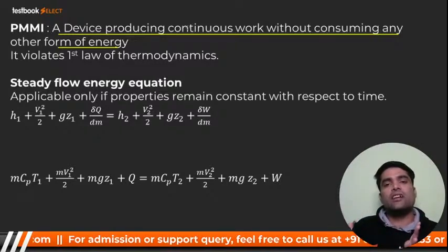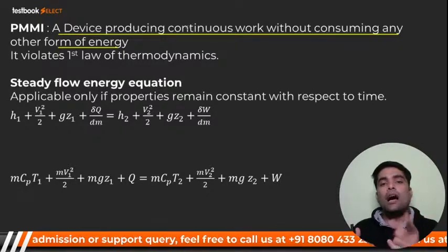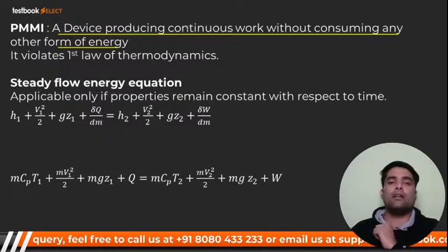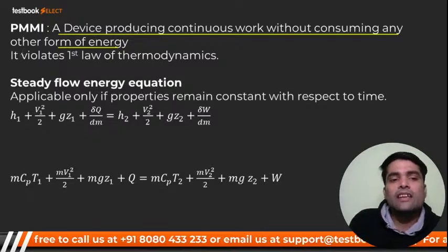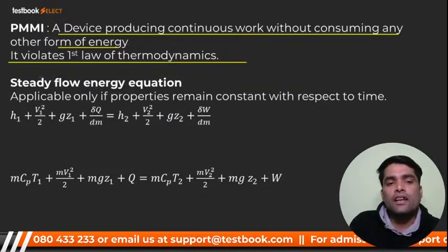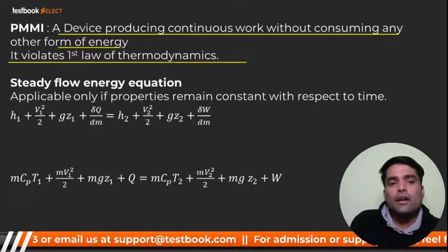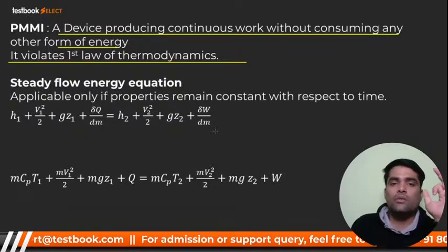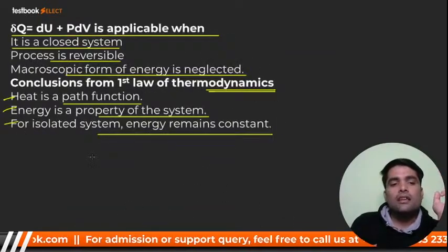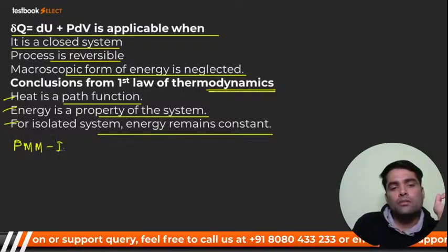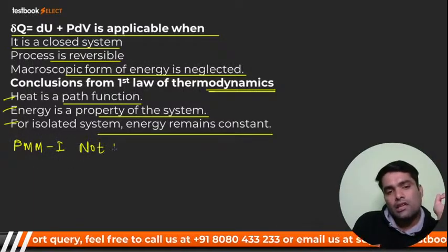लेकिन जब इंटरनल एनर्जी खत्म हो जाएगी आपकी बॉडी के अंदर की, आप गिर जाओगे नीचे. सो दैट्स व्हाई कंटिन्यूअसली पॉसिबल नहीं है, बट पॉसिबल तो है, राइट. सो उसको डिनाई किया उसने, इट वायलेट्स द फर्स्ट लॉ ऑफ थर्मोडायनामिक्स. सो डेफिनेटली इट इज नॉट पॉसिबल. पीएमएम 1 भी बोला गया कि फर्स्ट लॉ के कंक्लूजन में आप एक चीज ऐड कर दीजिएगा कि ये पीएमएम 1 इज नॉट पॉसिबल, ये भी बताया गया था इस लॉ में.